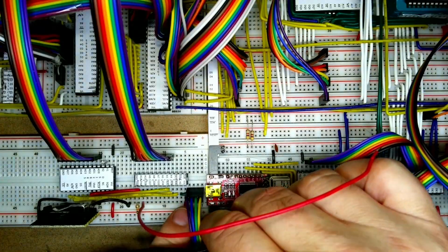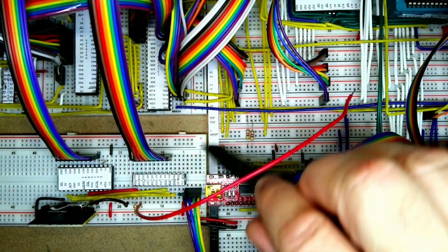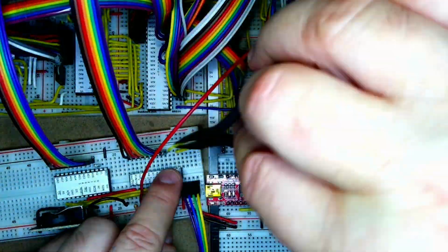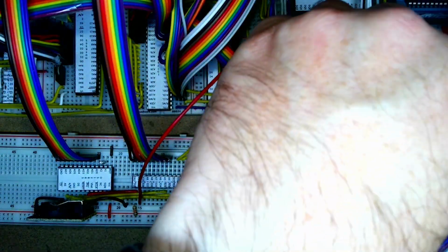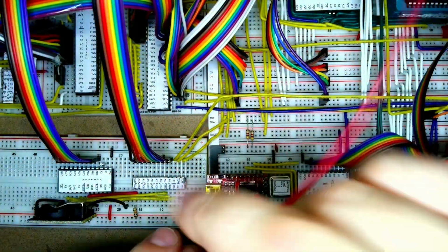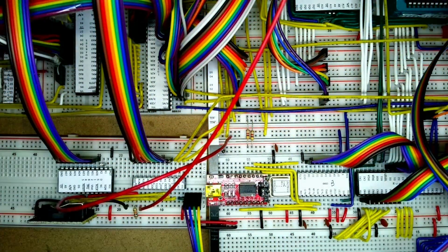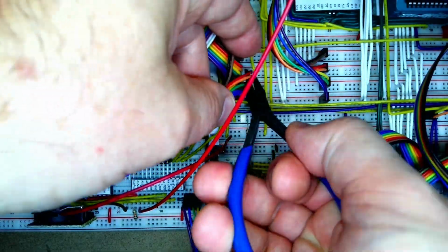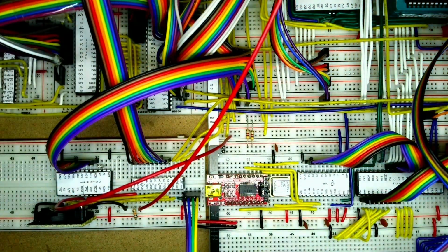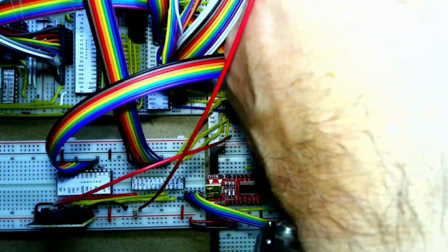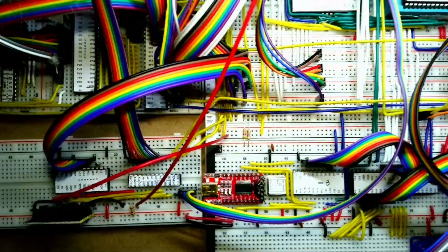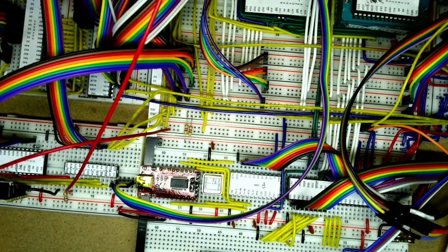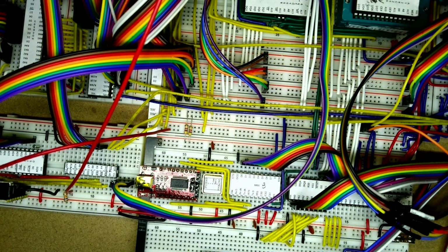So just connecting up the power lines there temporarily, then feeding in the IO read and IO write. And this is the address line A12 to A19 signal, the reset and the interrupt lines, and now we're just wiring in the data lines here, and then these are the A0 to A3 lower address lines, then finally the higher address lines that go a bit further up the board. They're out of camera view. Okay, so that's all wired in now.